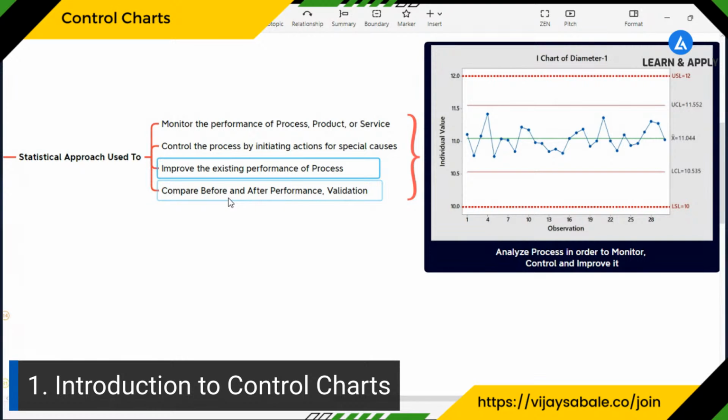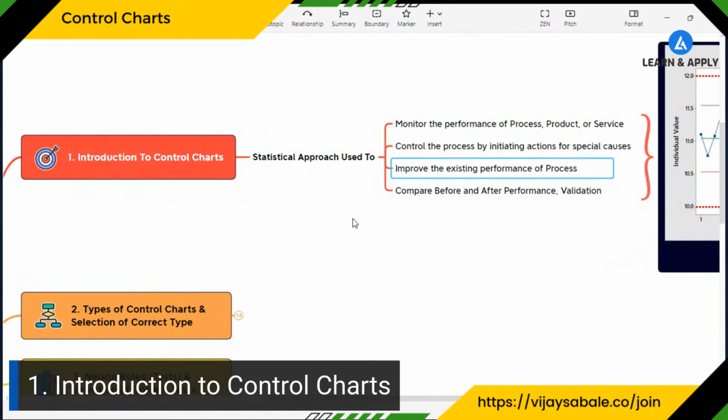Here is a typical example that I have shown of what a control chart looks like. It has some average, it has the upper control limit and lower control limit, and we are going to compare those with respect to the specification limits. The specification limits are specified by the customer, whereas the control limits are calculated based on the data points or the observations that we have collected. So we can say, to analyze a process in order to monitor, control, and improve it, we are going to use control charts. And again, if you want to compare before and after performance, or if you want to validate our actions, again, we are going to use this important tool, control charts. Is this clear?